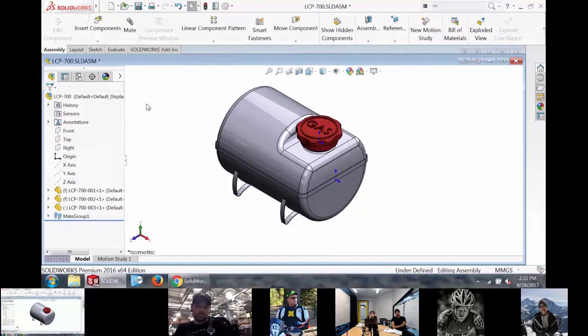So how do you get around this? Don't name stuff cap, pin, gear, wheel. Those are terrible names. All you need to do is put your initials at the end, put today's date at the end, put some modifier where nobody's going to get that same combination of letters in there. The best one would be to use a GPN, because if you have a real part number, obviously nobody's going to duplicate your part number.